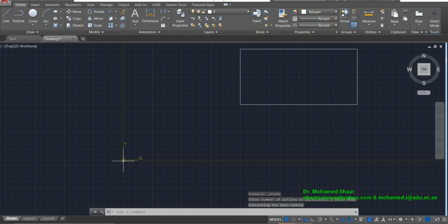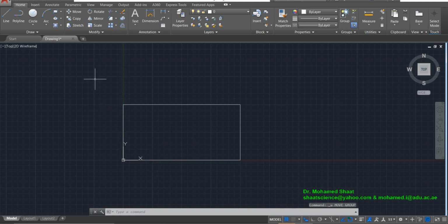So in this case, you could use the move command with an option in this way, and this is the way that there is d, the square root of x squared plus y squared. This is the method that AutoCAD used for doing the calculation of the displacement that this object should be moved with. Make sense? So this is basically for the move command.